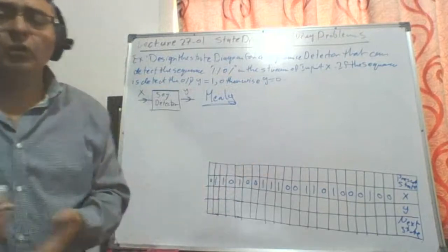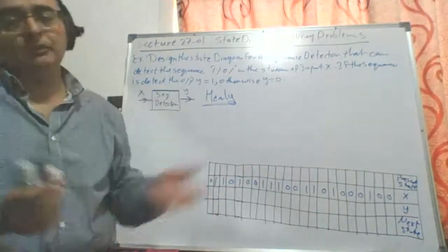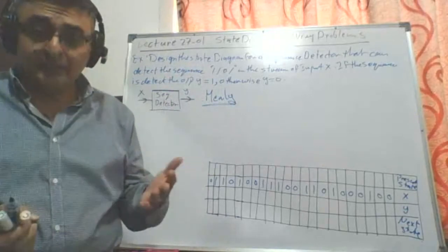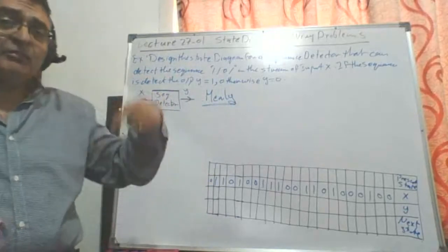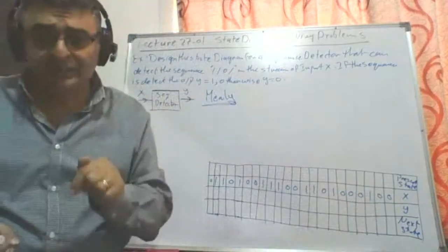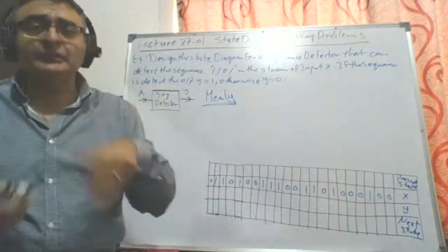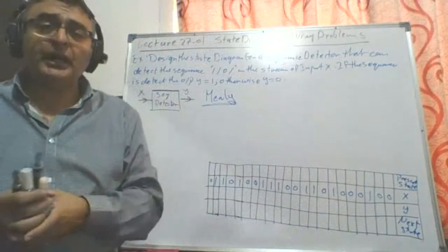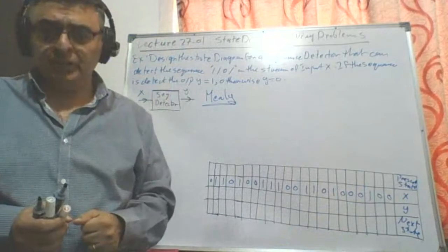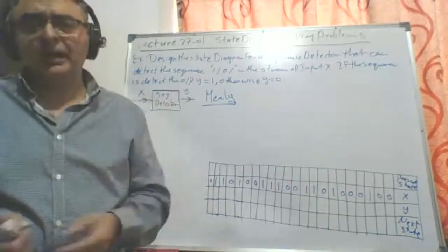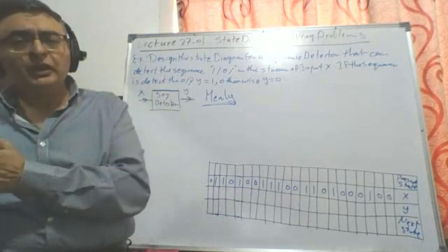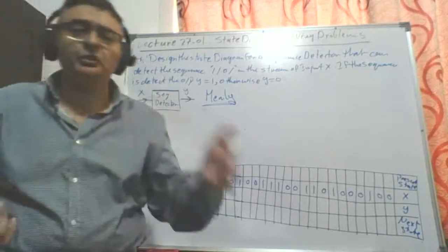So first of all, why is this a sequential circuit? Definitely because it's called a sequence detector, but because actually the value of Y at any given time depends on the current value of the input and the previous values of the input. So the circuit has a feedback. I should remember what the old values were in order to decide the new value.